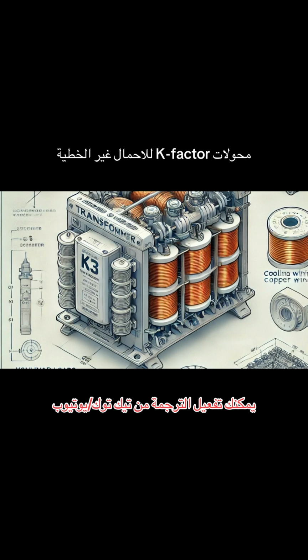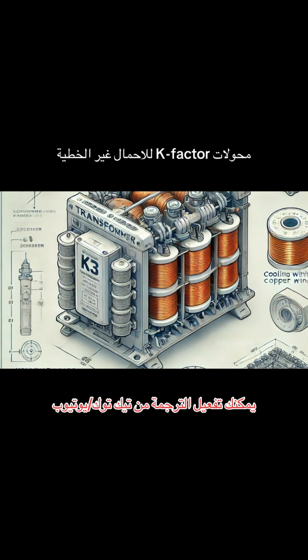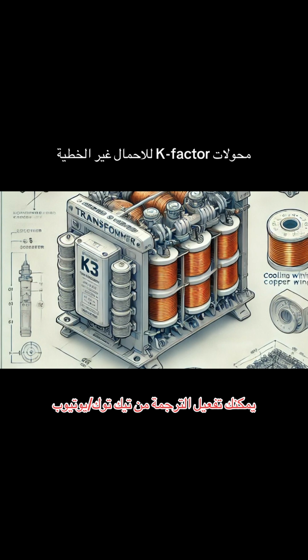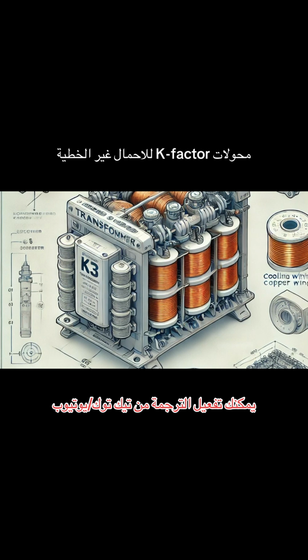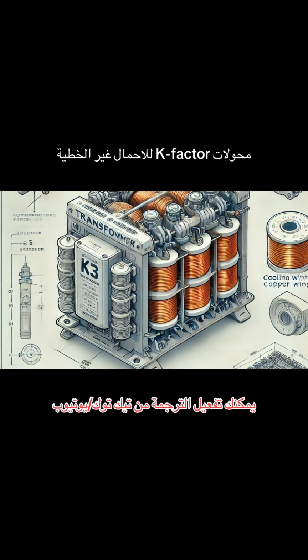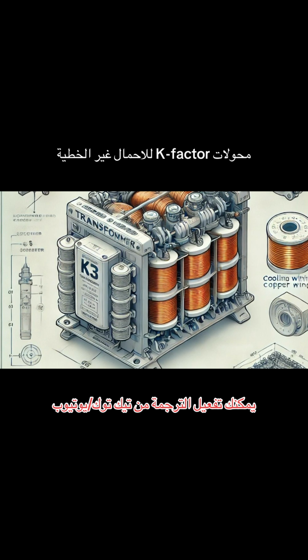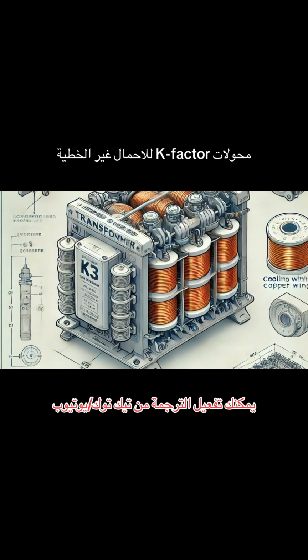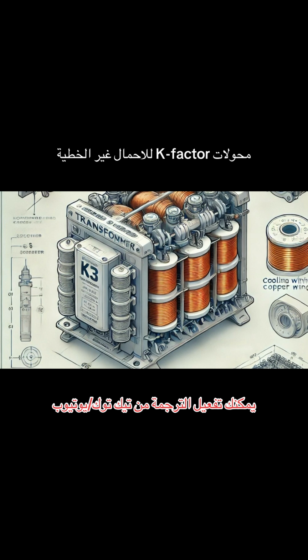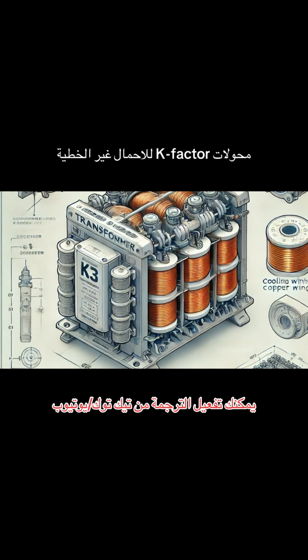And now here's where it gets really important and why everyone listening should pay attention. In a standard three-phase electrical system, which is what most buildings use, these triplen harmonics don't cancel each other out like some other harmonic frequencies do. Instead, they add up, and they add up specifically on the neutral wire. Wait, so they combine forces on that neutral wire? That's kind of counterintuitive. It is, yeah.